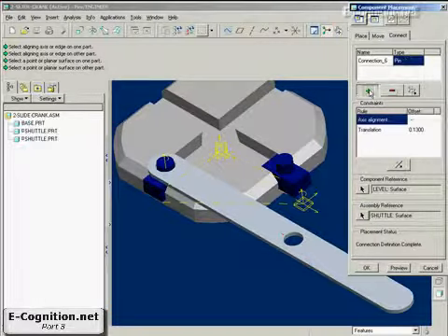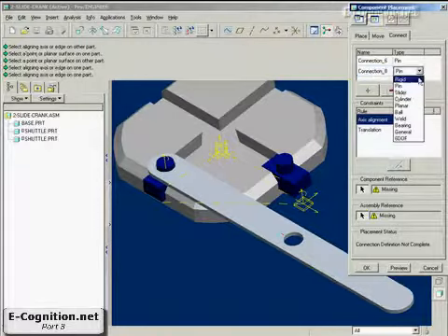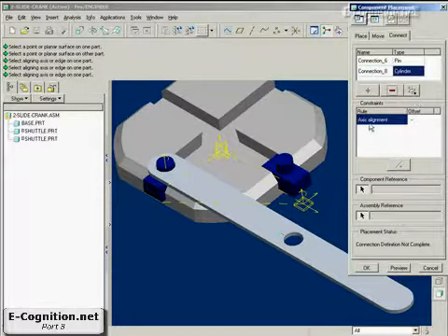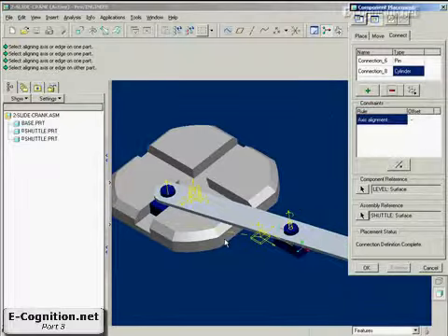We're going to add a second joint now. If we add a second pin, the translation aspect of the pin joint will be redundant, so I don't want to add a second pin. I want to add a cylinder, which requires an axis alignment but does not require the translational component. So I'll connect this cylindrical face to this one. That ties them together. Call that OK.